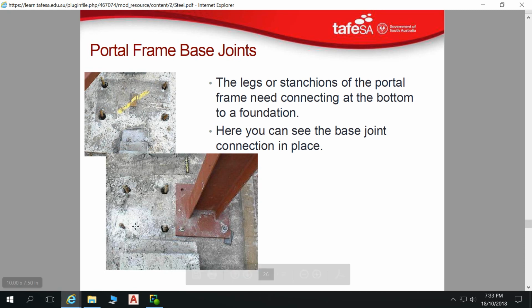They require a lot of restraint. They require a lot of tie down. That can be achieved when we've got our threaded rod cast into our concrete footings with a cog on the end. You can't pull that out. And it's about the strength of that steel. It's about that steel snapping before you pull it out.